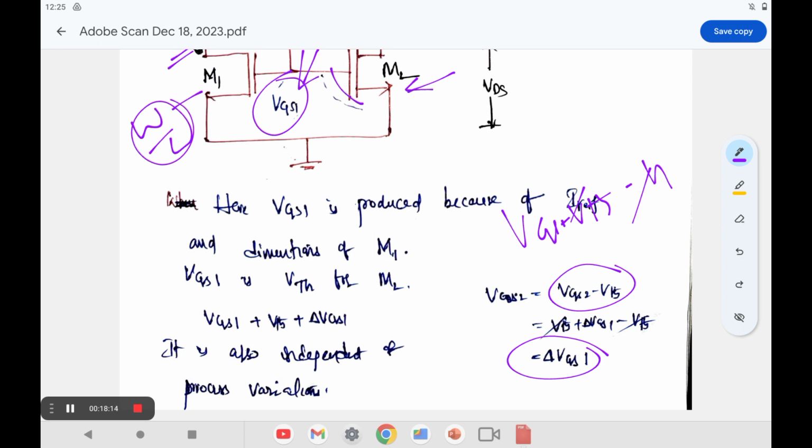So where are current mirror circuits used and what is the problem with them? The journey starts from somewhere else. If you take a small resistor, from resistor to second stage, in the case of the resistor, the complete value can be decided by itself only. That is also one of the drawbacks. So in the second stage, we will take a transistor, from the MOSFET point of view. These transistors and MOSFETs also depend on the biasing and the nature of the devices. Biasing elements also depend on temperature variations and supply voltage. So some more circuits are also required to produce a constant current.